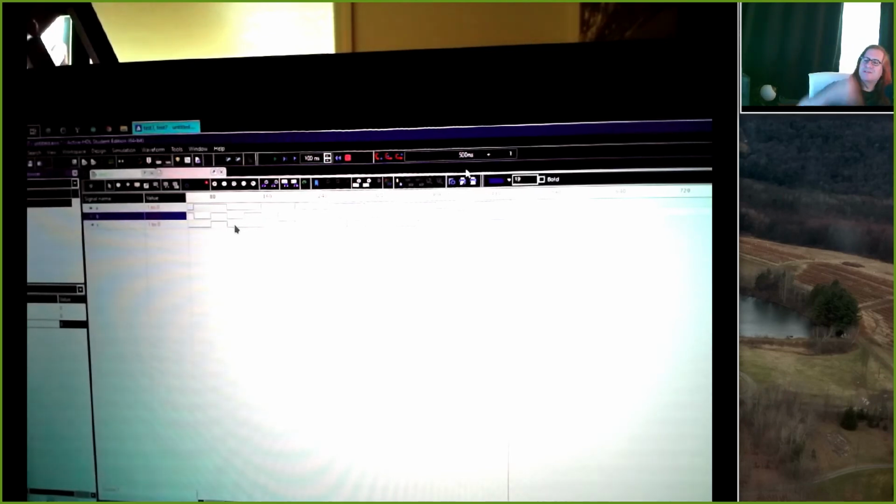Okay, those are the basic steps, and I have a quick start. I think I put it on Canvas, but if not, I'll post it and I'll send an announcement that goes through each of those steps that we just did, including setting up those design access checkboxes, and then, you know, doing file, new waveform, simulation, initialize simulation. I'll post a document that specs those out. So if you didn't catch all of that, you can read it from there. But that's it. That's the whole start to finish example.